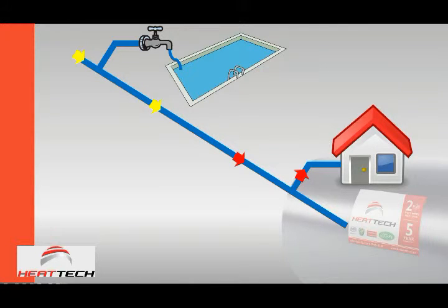In the next slide you can see that dirty water, now that the pressure came back, is now flowing in the same direction that water would have flowed. But there's a strong possibility that water would now be flushed back into the household. It gets flushed down the line, down the municipal supply line.